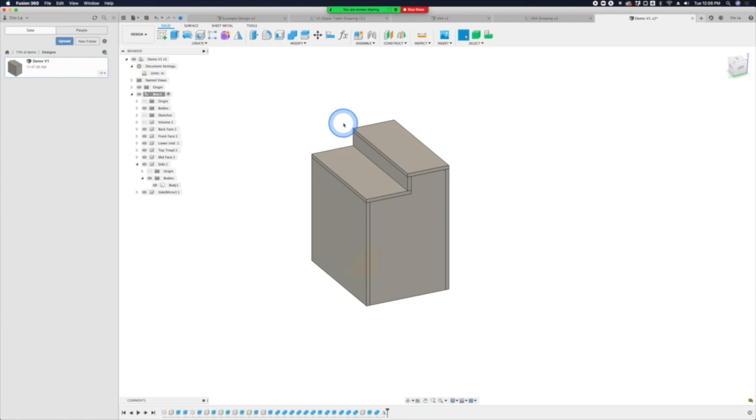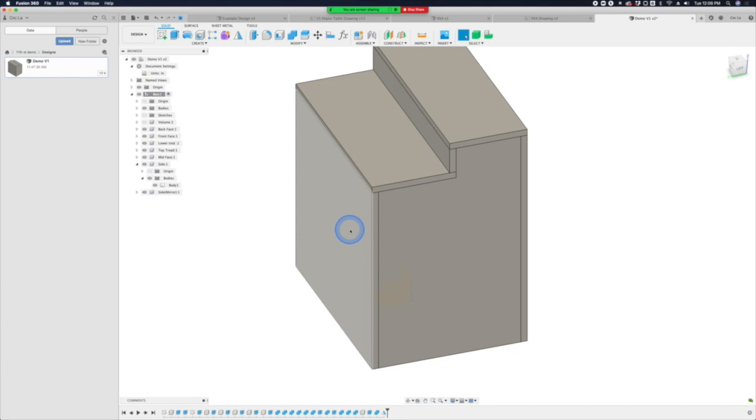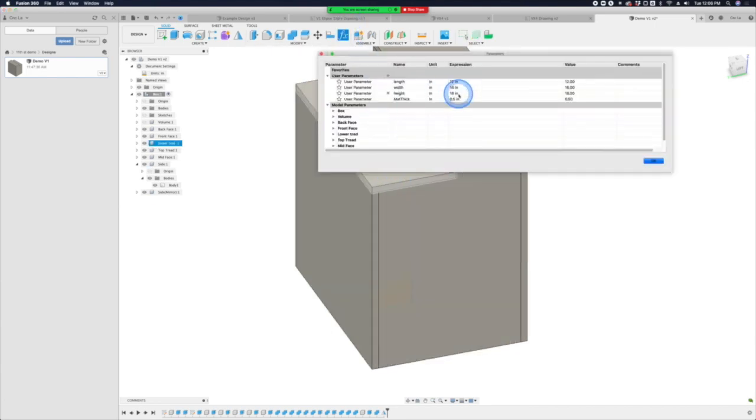Yes, because you're drawing from that face outward. Basically, this plane is fixed. Because I drew in from it, it's not going to move in space. But if you drew out from it, that plane would still exist there because it is essentially defined by our sketch. So if I also went in and said, let's say the width of this box is different and it's 24 inches now.